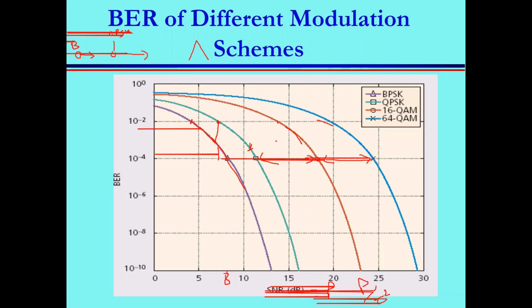What about small scale fading? How does this happen? You want a fixed bit error rate. The user is here. This is the base station. The other example. This is the base station and this is the user. At time t0, the user has this channel, low quality, low amplitude. So the base station has to use what? Lower order modulation to achieve 10 to minus 2. After 5 seconds, after 1 minute, the channel improved because the channel is time varying, yes? Changes with time. Improved. He is still in his location.